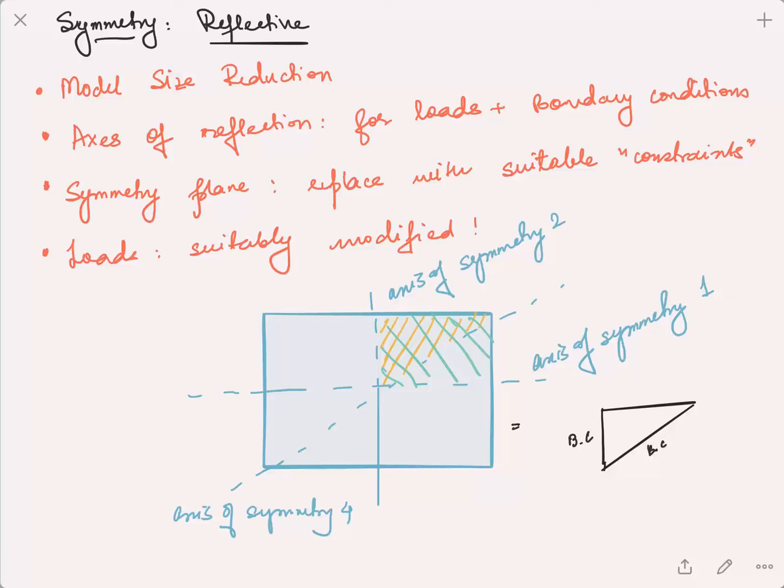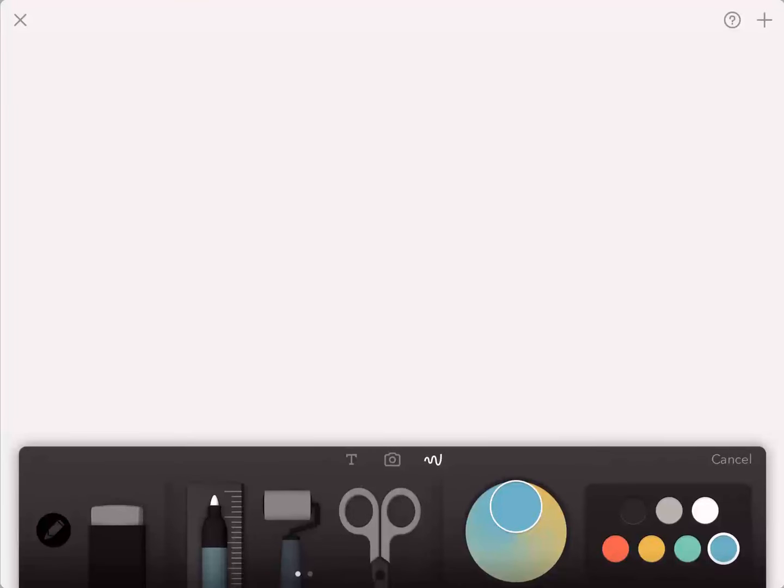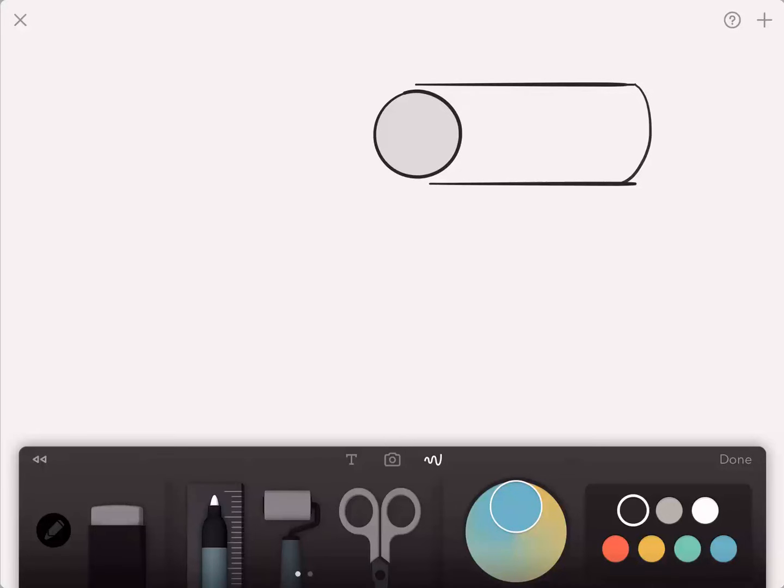So what you start doing then is thinking of smarter ways of reducing the size of the model by picking up certain sections which may be either repeated or have the same loads or can be just assumed to be simpler in a form of idealization. So what I ended up doing in general, let me show you a picture. If I had a complete fuselage section which looked somewhat like this, and there were of course frames and a floor beam and all kinds of vertical stanchions, all of these were present in the model.